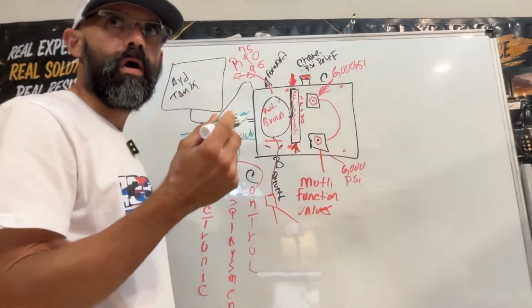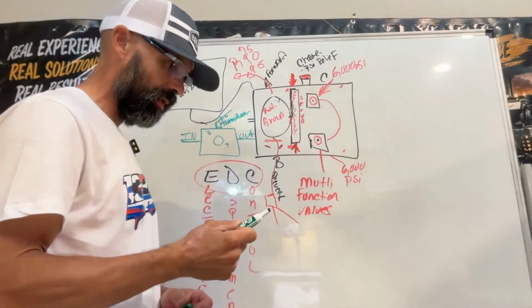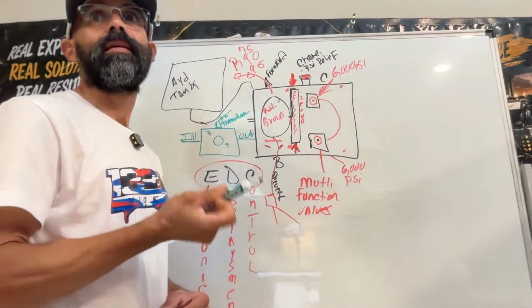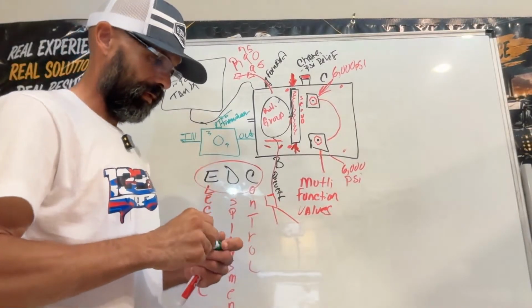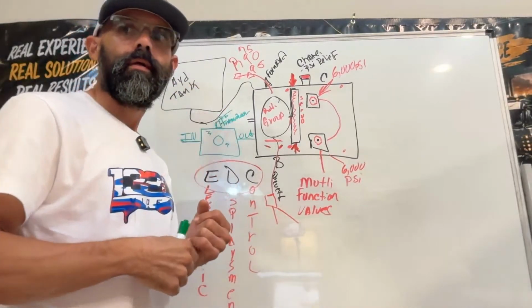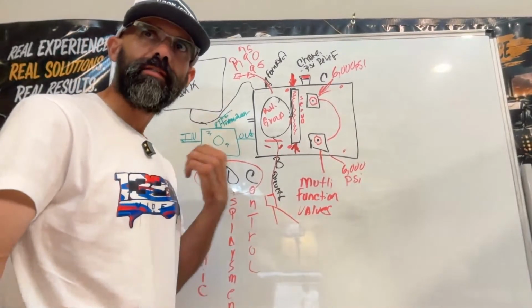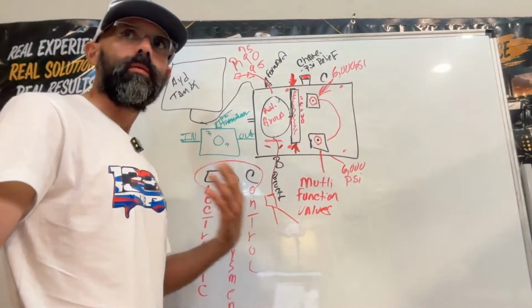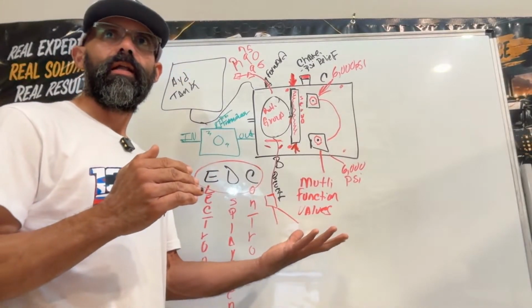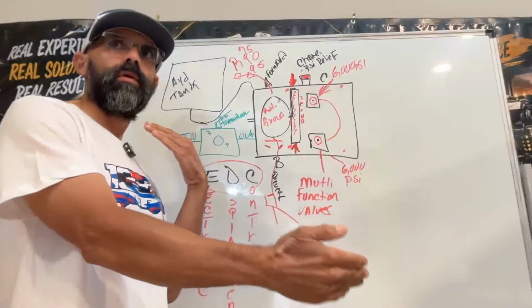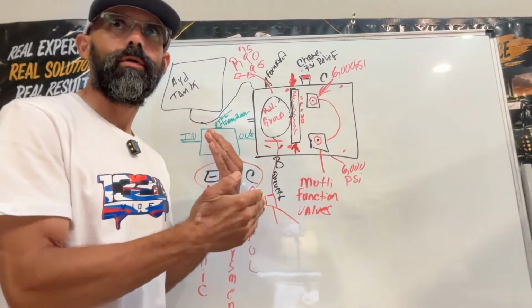You gotta have three wires. You're gonna have your ground, power, and signal, right? Because you gotta see, so you can translate basically the hydraulic pressure into an electrical signal, and that's how you get your reading on your digital display.